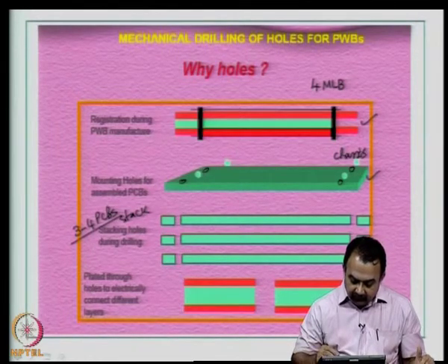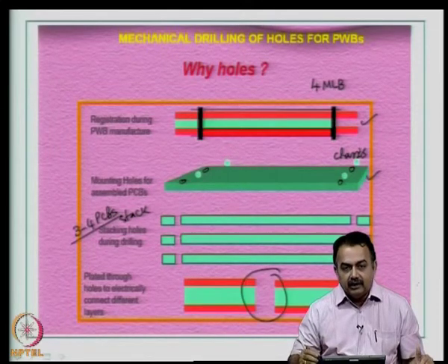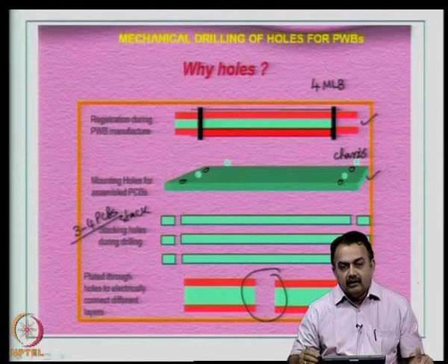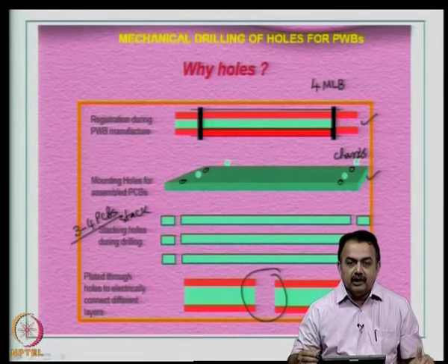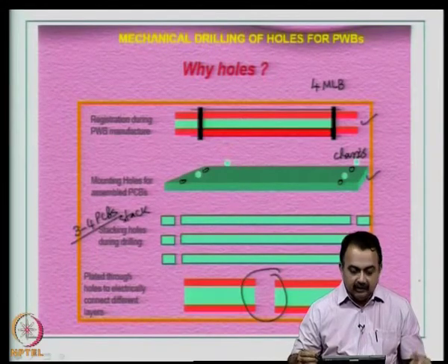Finally, the important thing is you drill holes so that you can create plated through holes, and the post drilling process would be to make sure how well you can prepare the hole wall for plating.